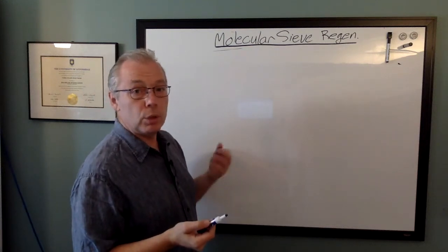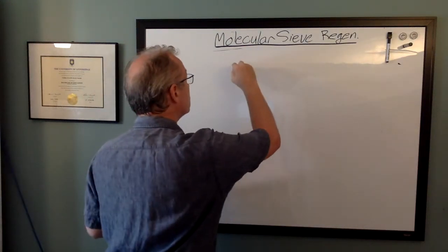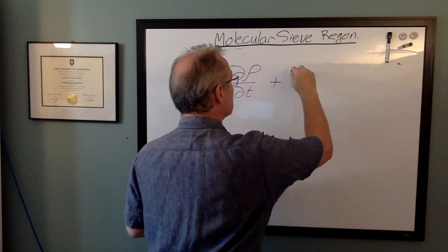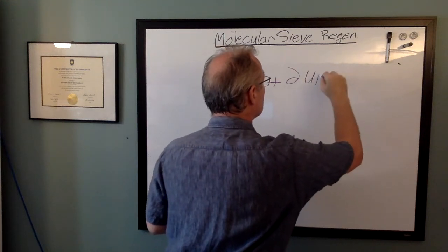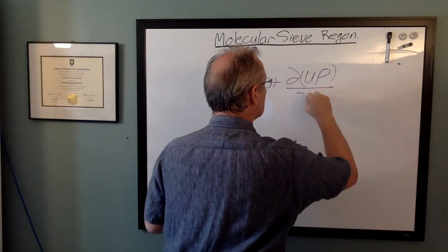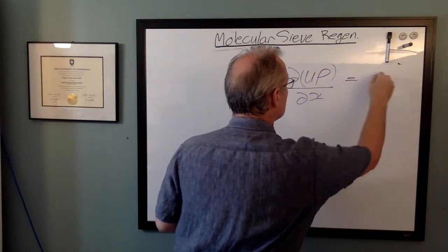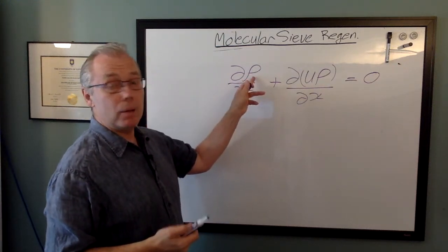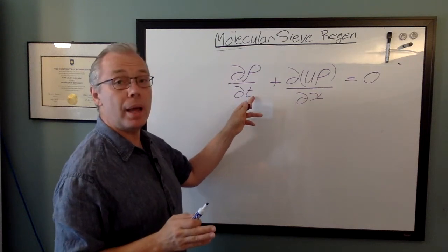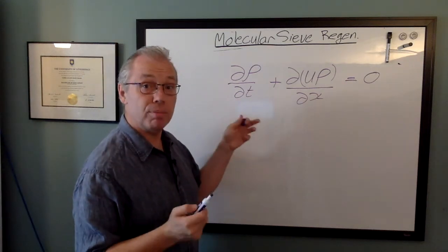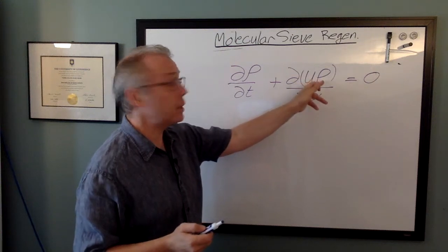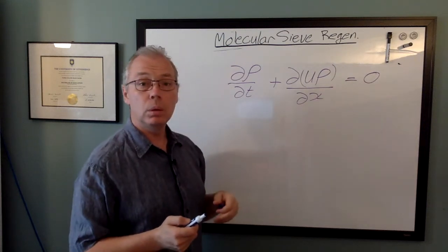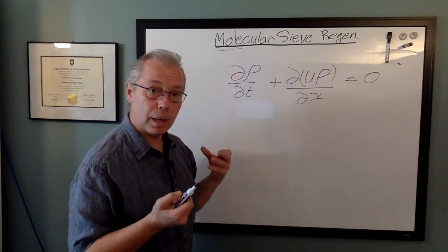One that we need is the conservation of mass. And this just says that the change in mass, the change in density per unit time, is equal to the change in flux of mass flow rate, or volumetric flow rate and density, over the volume of our domain. And that's equal to 0. So now we have an equation for how the density changes.